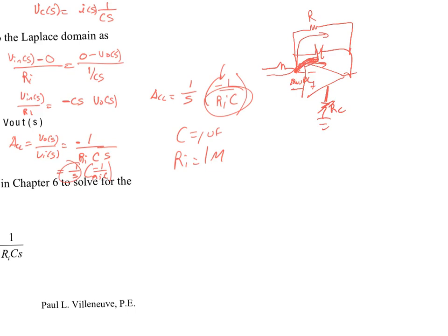Do you remember? How do you size this resistor? Did John talk about break frequencies and all that stuff? No? What's the definition of a break frequency or cutoff frequency? There's another term for it called the half power frequency. Half power means when 1/2 the power goes here and the other half goes here. How do you make 1/2 the power go through each element? Just need to match the impedances. You make R equal Z, right? Whatever the impedance of the capacitor is. So whenever you have those equal, half the current's going to go through one, the other half is going to go through the other one.